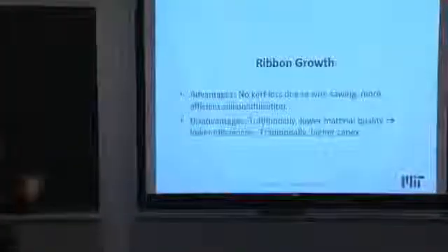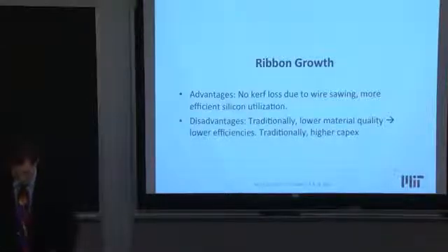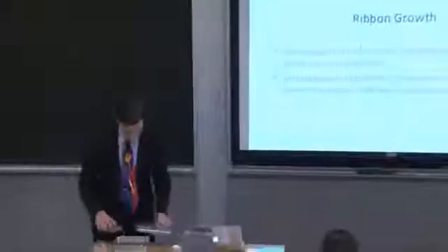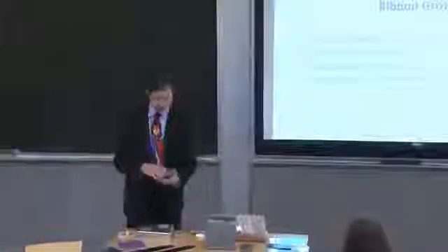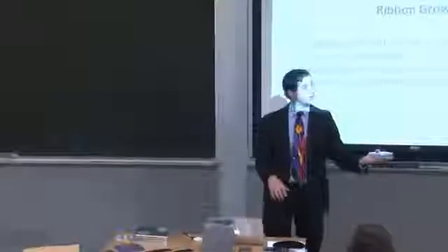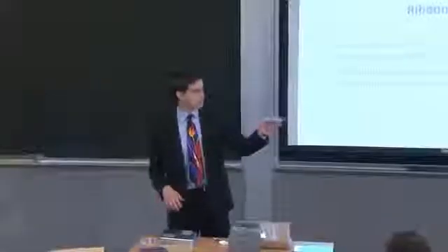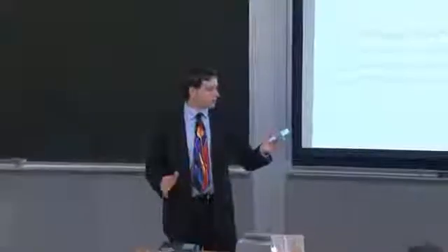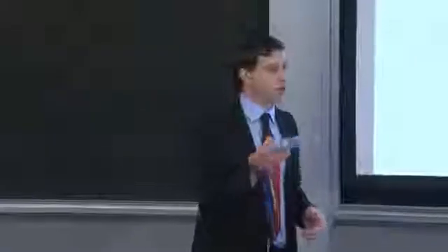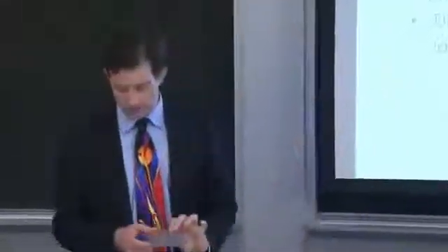And what we've done, just to resituate ourselves, we talked about the silicon feedstock, right? So we chatted about how you go from quartz in the ground and the carbon-bearing feedstock material to the heavily purified silicon feedstock material. This right here is probably on the order of somewhere between 8, 9, or 10 nines pure, very, very pure material. This Siemens grade polysilicon right here in my hand.